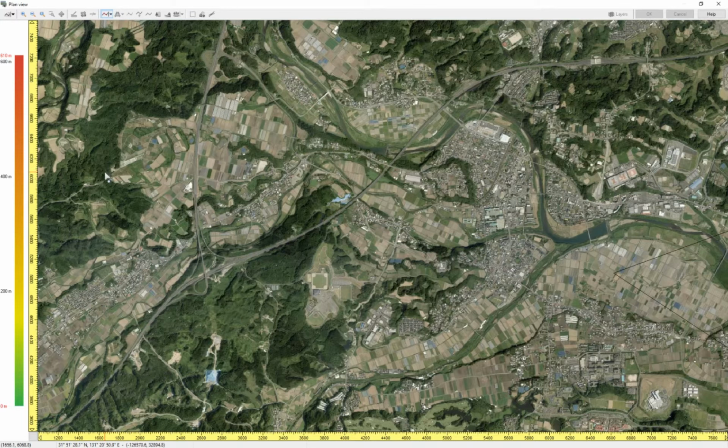So once you select Make Road, you have your mouse cursor changing to road defining mode. If you click somewhere, it will define the first point of your road, and until you click on the second point, it will wait to actually create the road. So I click on the second point here. It defines a second point for the road. When you have 2 points, it actually creates a straight road between the 2 points.